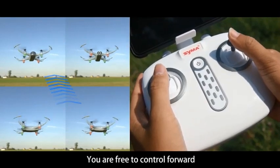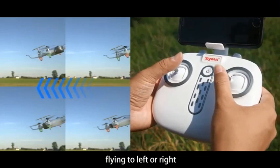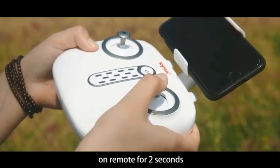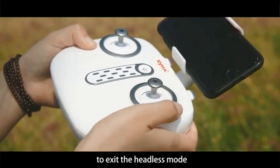You are free to control forward, backward, flying to left or right. Manually press the right joystick on the remote for 2 seconds. Wait until the remote control emits a long beep sound to exit the headless mode.